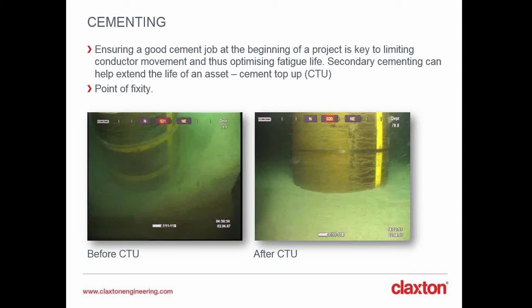So cementers will typically pump a considerable percentage of excess slurry as a standard practice. But this percentage will also depend on several factors to do with the formation characteristics, for example if it's an area that loses a lot of fluid. Prior experience in the area is important as well. If it's not a new well, then there will be records of how the previous primary jobs went. As an additional contingency, a secondary system to deliver the cement to the top section of the hole might also be considered.